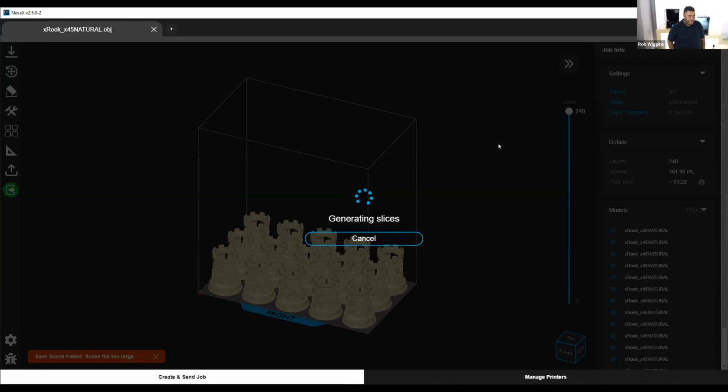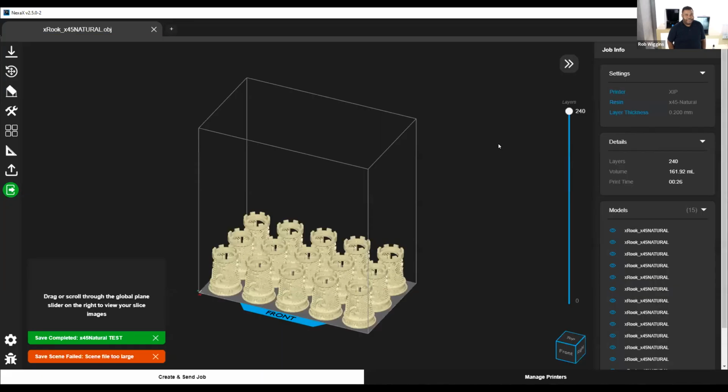I've modeled in some holes actually in the bottom of it, and that was just to not use as much resin on just having a solid base. I like to conserve resin wherever possible. And with something like this, because it's completely unsupported, in my opinion, it leads to a better print. For sure.